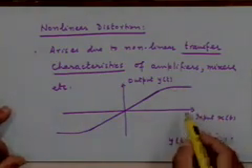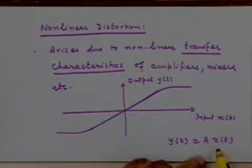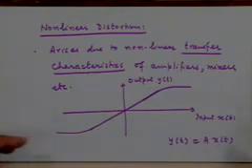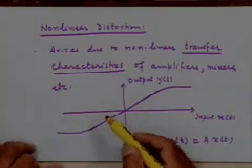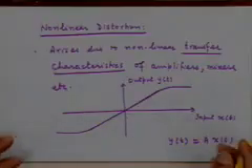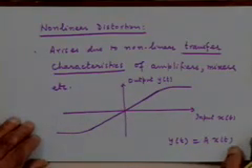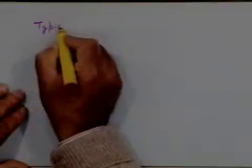Now basically if you were to model this nonlinearity, you can see that you cannot model it as a straight line kind of relationship, a linear kind of relationship of this kind. Can you suggest some model for this curve that you have here, some suitable parametric model? For example, we can possibly model it as a polynomial of some kind. We can find out suitable coefficients of a polynomial such that the resulting curve would look like these characteristics, and that's a usual thing that is done to model nonlinear components, nonlinear devices, right? Use polynomial models.